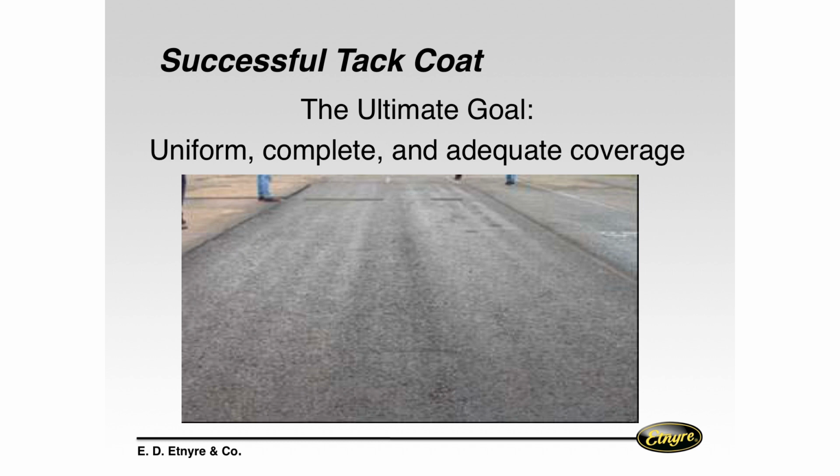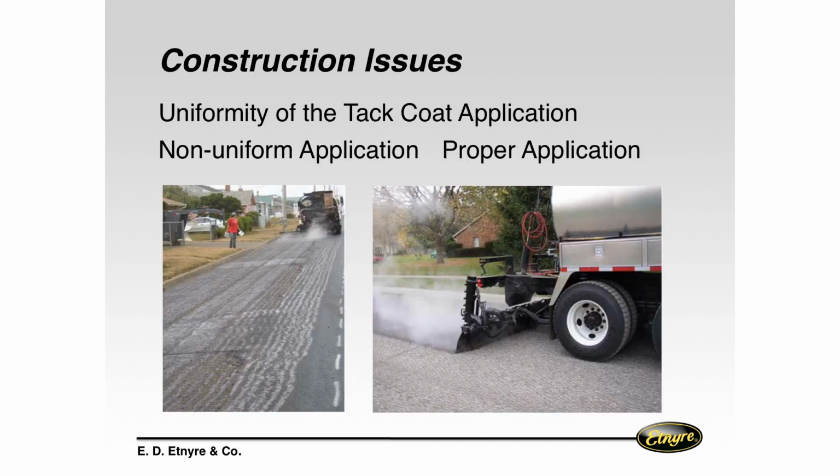Just like you took a paintbrush out there and painted the stuff on the surface, that is the ideal tack situation. Adequate coverage from one side to the other. So back in the old days when we could just string it out like this picture, those days aren't there anymore. We have to have uniform coverage, because in any one of those spots where we have no tack, that asphalt's liable not to stick to the base layer, and it's liable to come right back off. So we've got to have that uniform application.